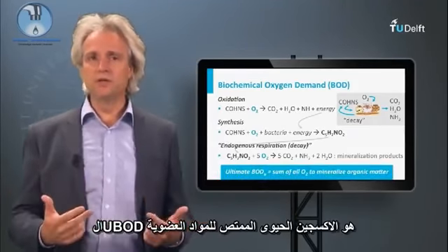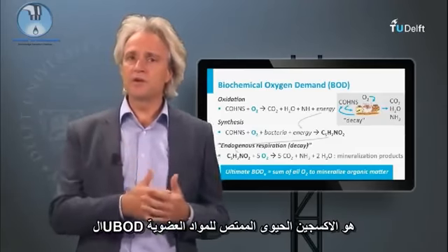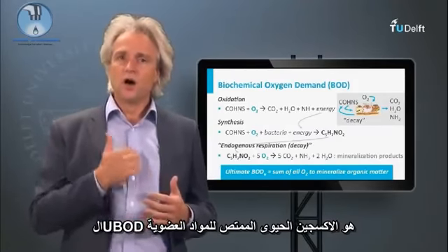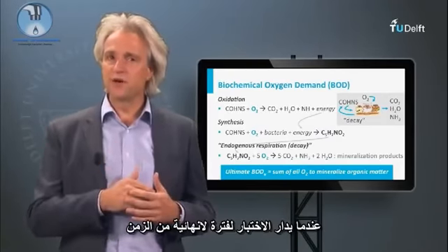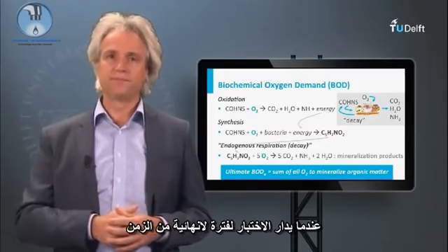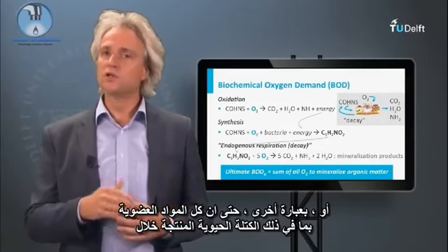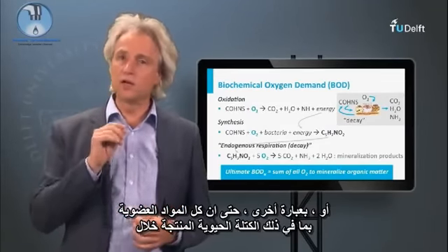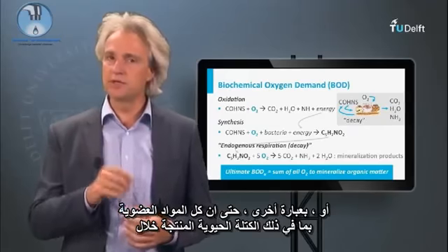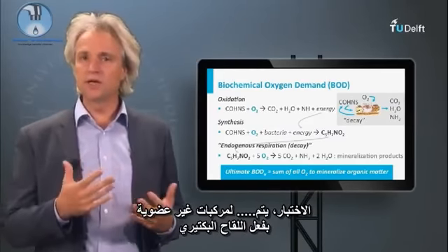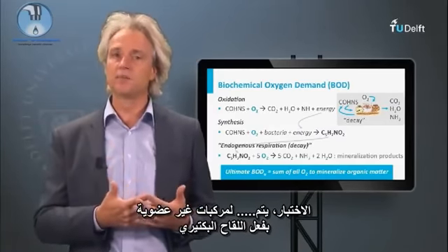The ultimate BOD, therefore, is the biochemical oxygen demand of the organic substrate when the test is followed until infinite periods of time. Or in other words, until all organic matter, including the biomass produced during the test, is mineralized to inorganic compounds by the bacterial inoculum.